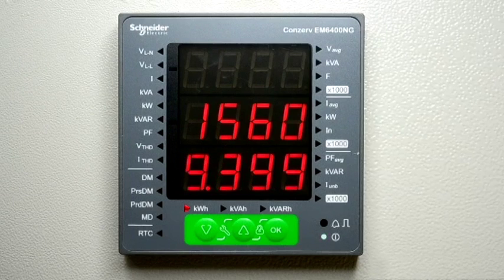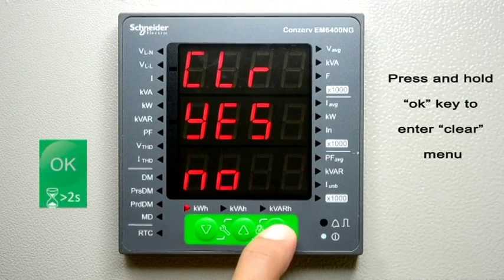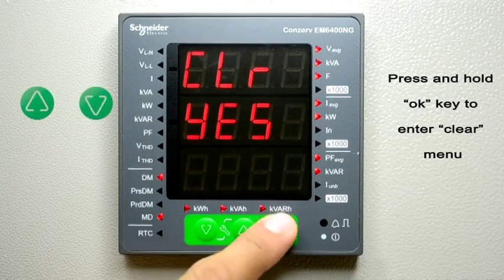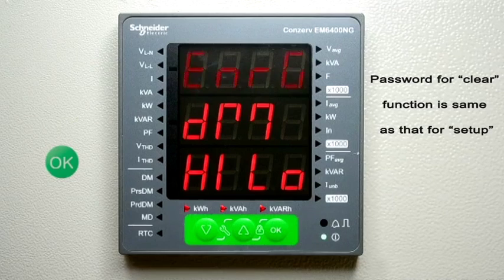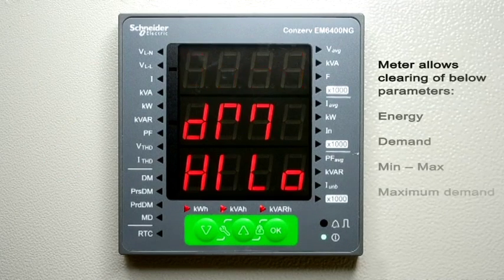Let us now see how to reset the accumulated values through front panel keys. To reset the accumulated values, press and hold the OK key for 2 seconds. The meter asks for a confirmation to enter into clear menu. Select yes and press OK. Then enter the password and press OK. You can now choose the parameter that you want to reset.